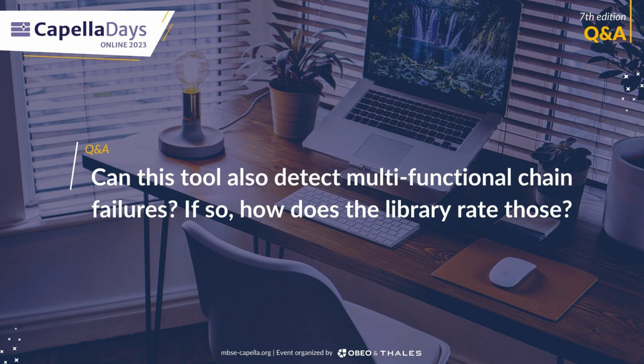So if you mean if there is any interaction between the functional chains, then this is only considered if the exchange scenario contains a reference operand to the other exchange scenario. I don't know if that's clear enough. It's the same as when you introduce a loop or an alternative operand, you can introduce a reference from one exchange scenario to another, and that's how the algorithm connects the exchange scenarios to each other during the same scenario breakdown, or else the analysis will be separate.